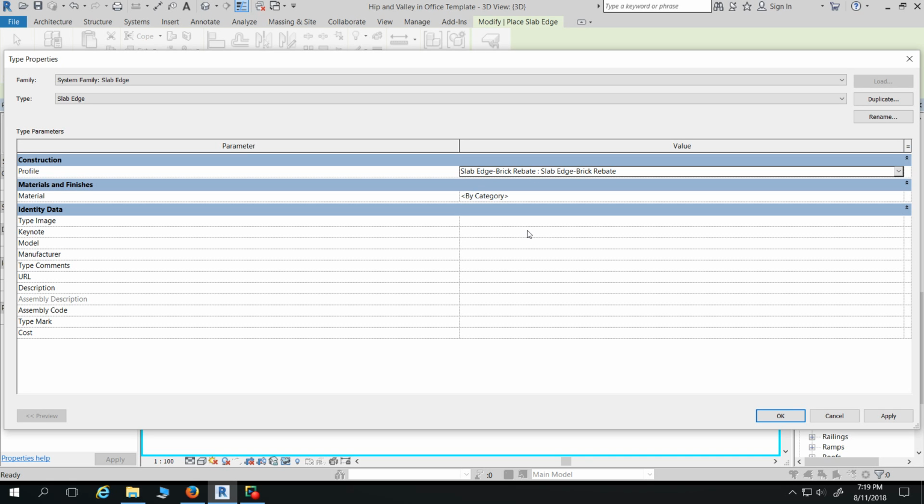On the learn site there's one. So we go to the learn site and download the file. And save, and okay. Then just go back to Revit, Insert, Load Family. Find wherever you downloaded it, on your computer, Downloads. You've got it loaded in.